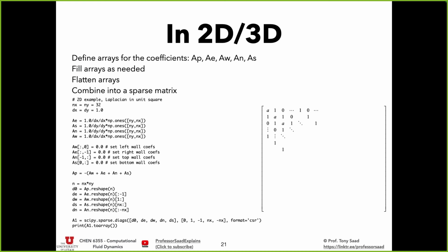Now, this is what we will be using when we go back to our finite volume solvers. This is going to create a matrix, and that sparse matrix we will use with some really cool iterative solvers. We're going to be doing multi-grid, conjugate gradient, sparse solves. It's a really bulletproof way of thinking about how to build that matrix for a 2D problem. I've avoided it so far because SOR and Gauss-Seidel are pointwise. But the advanced solvers need a coefficient matrix, and this is the way to do it.